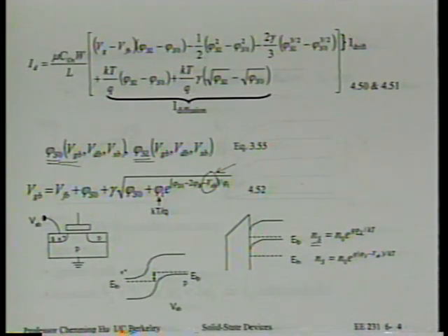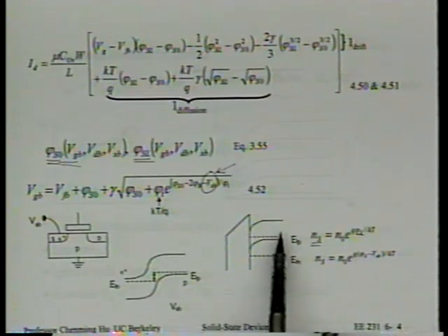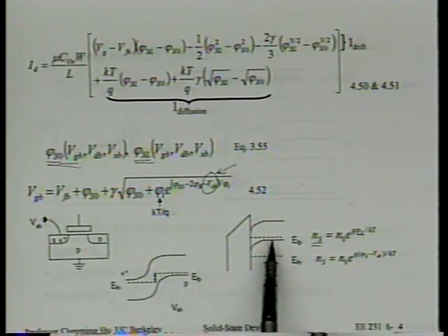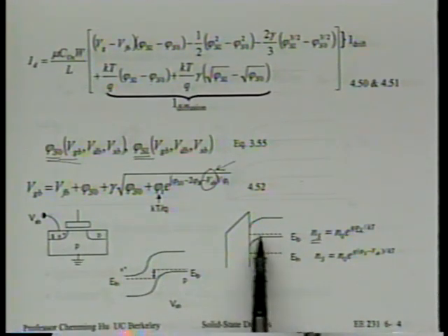Now the question is, which of these two Fermi levels will determine the electron concentration? Is the EFP, which is pinned to the body, you see? The usual Fermi level we drew now has to be called EFP, because this is the energy band diagram of the body, yeah? So the Fermi level that's close to EV of the body, that's our EFP.